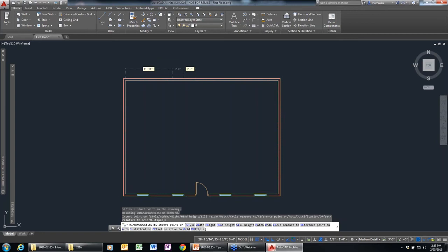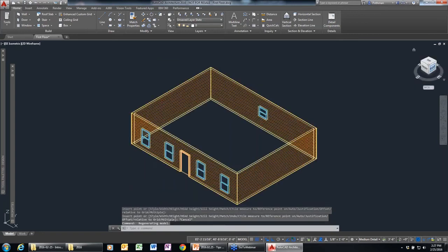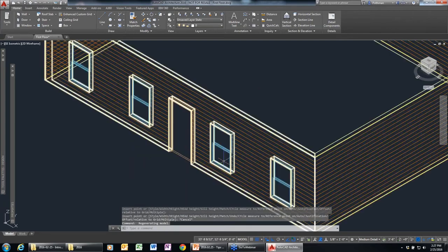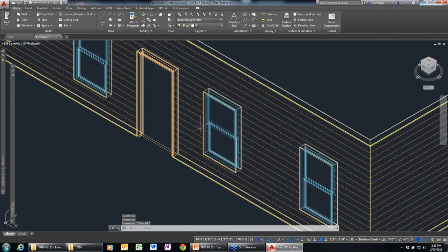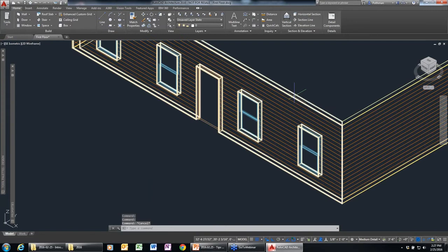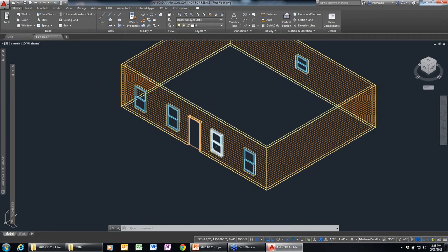And let me see, if I just flip to a viewpoint here, you'll see that now I've got my double hung windows, which are probably flipped around backwards. Should be the top panel on the outside, but again, swapping something like that is just hit the flip grip and you can fix the panels there. But then I have my 3 foot window, which has the same head height, but it's only 3 feet high instead of 5 feet high. So very quickly I'm starting to lay out a very simple design. And certainly AutoCAD Architecture does a lot more than residential design.